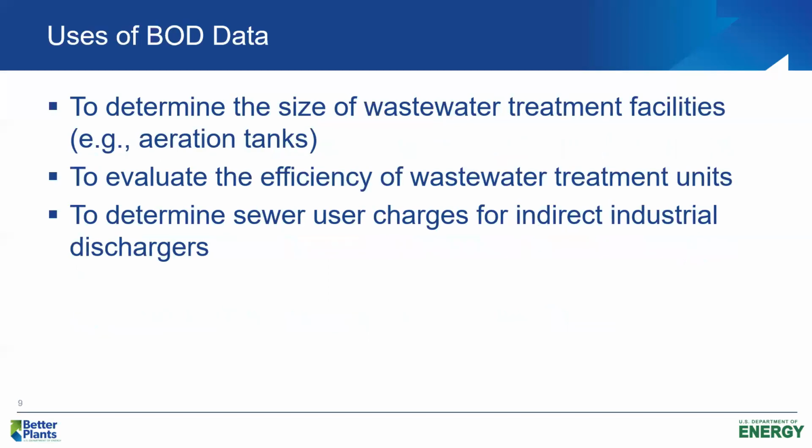But we also use BOD to determine the quality of our effluent, and it's important for that as well. We often size our aeration tanks using a term called volumetric organic loading rate. Whenever we design an activated sludge process, it's important that we look at the VOLR, the volumetric organic loading rate. It is the pounds of BOD5 per day applied to the aeration tank, and it's in per 1,000 cubic feet. So it's pounds of BOD5 per day per 1,000 cubic feet of aeration tank volume. Call it the volumetric organic loading rate. It's an important design parameter.